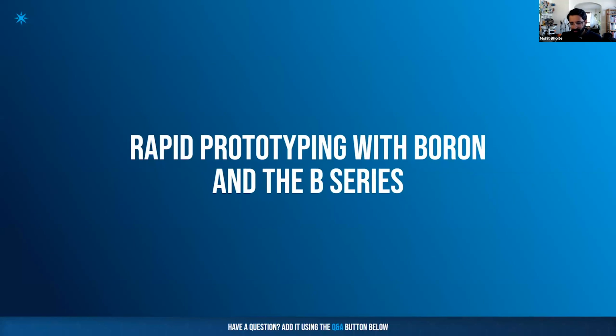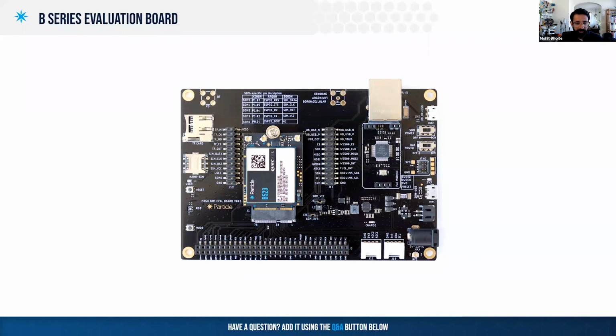All right, now that you have narrowed down the parts, you know what the architecture looks like. Are you then going to jump directly into designing a PCB, or are you going to prototype these parts? An easy and quick way to prototype is using our evaluation board. You can just swap out this particular BSOM with a B402. Either way, it should work. It exposes all the GPIOs, and also allows you to inject 3.3 V or VCC power if you want to skip the built-in PMIC. It also allows you to try external SIM cards and memory storage.